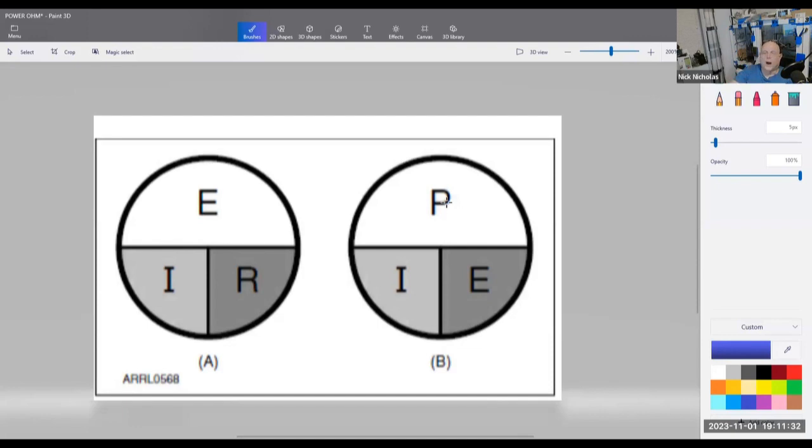Now, if you have to deal with a power formula, same thing. If they ask you, hey, what is the current in a circuit with X number of watts, that's power, and so many volts, that's current. So if they ask you to solve for current from power and voltage, again, you block off this one because that's what you're looking for. And the other two are the equation. P over E is equal to I. If you're looking for voltage, block that off. Imagine it's not there. P over I is equal to E.